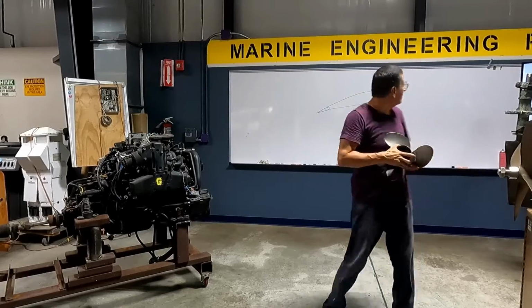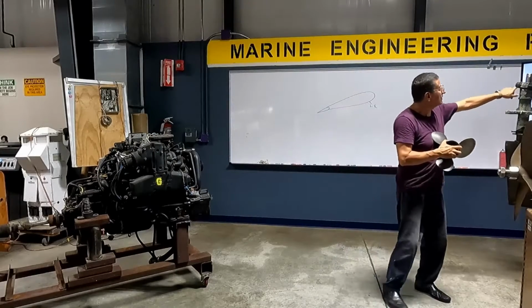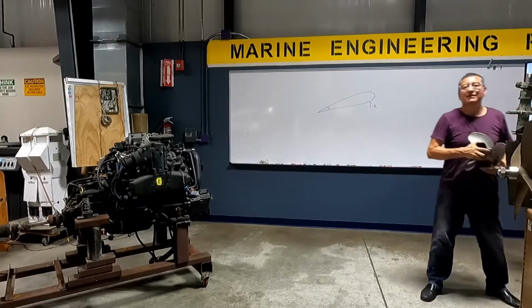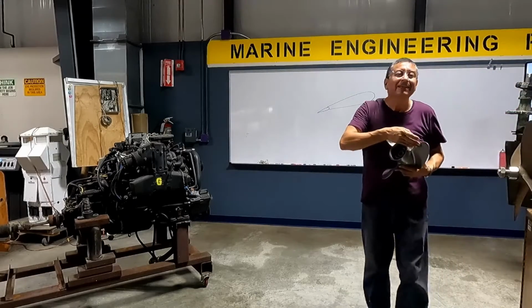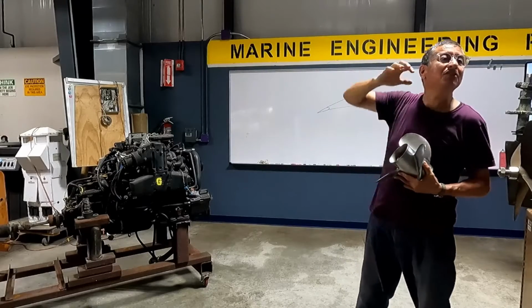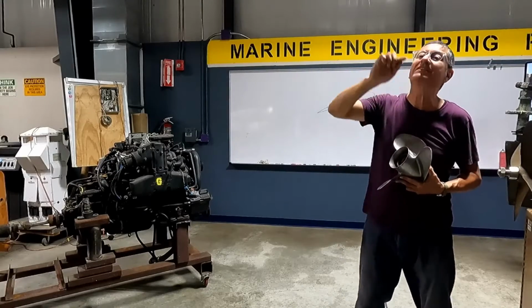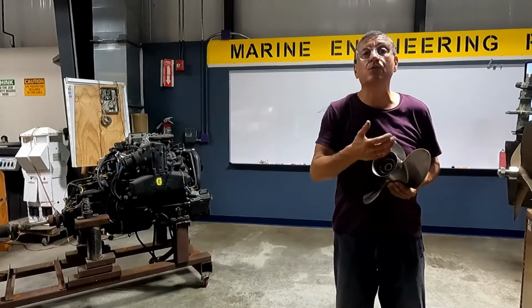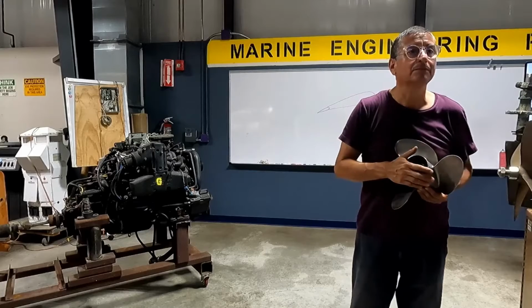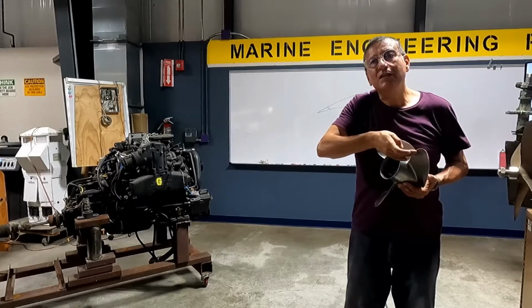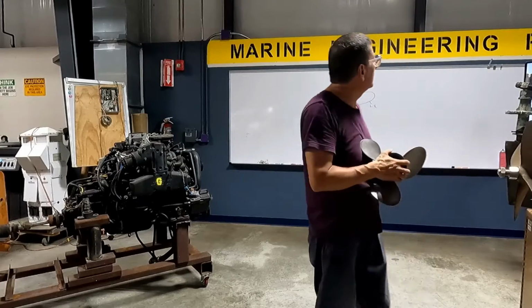This is the cup. That small inclination at the end. You see? This is trying to simulate that inclination in the leading edge on airplanes to increase the lift. In this particular case, it's not the lift, it's to increase the thrust. Those propellers have a little cup at this end, and this is the function.